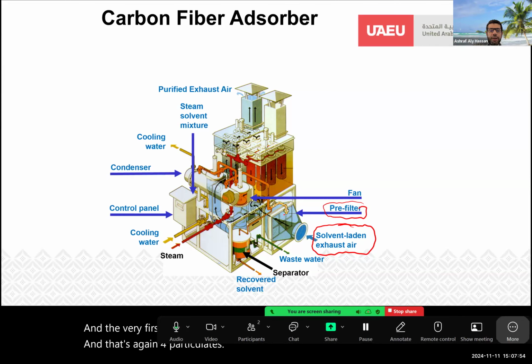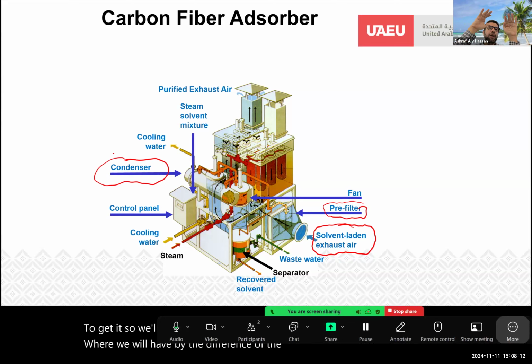The gas will go inside and we will try to condense out of it any liquid or any moisture that we can. So we'll have a condenser where, by the difference of the temperature, we will try to push down water or moisture out to leave only gas inside. Why do we do that? Exactly, because humidity decreases the retention.